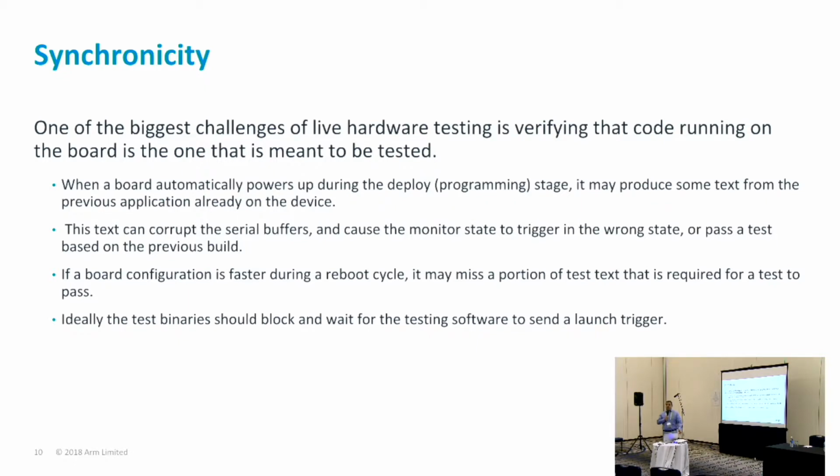On a similar side, if you have a board that will automatically boot and it is faster than the system expects it to be, assume that you have a delay between the deploy and the monitor stage, the board will produce some text that you're going to miss, and again, you're going to fail a test. It is quite important to be able to synchronize what is running and what the system expects. It would be ideal if we could just add a synchronization command that will tell the hardware to run the test now when I tell you to. But there are several implications that mean we cannot just do so.